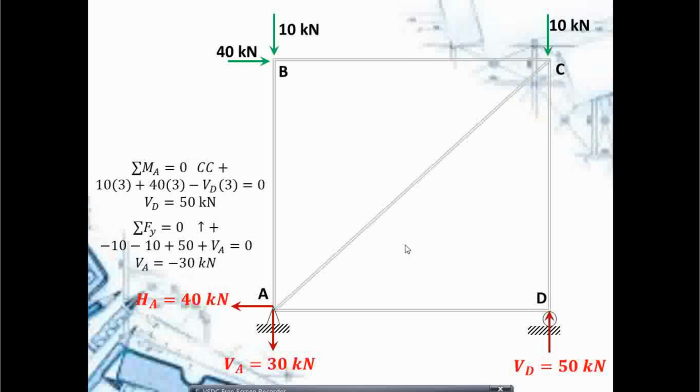Again, for the method of virtual work or unit load method for the determination of deflections for trusses, the first thing you have to do always is determine the support reactions. Next, after you determine the support reactions, you now need to determine the forces in the members, like in lesson 2, our previous lesson. Either you use method of joints or method of sections.